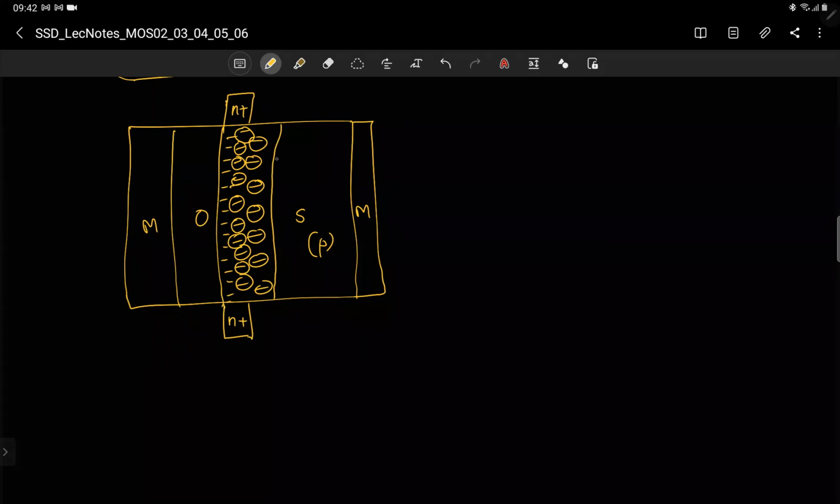If I want to contact a positive charge like holes, I have to put P plus. So in a realistic picture, how it is done is you take a semiconductor substrate, say P, and you grow oxide. I'm just giving steps, not in detail. All that process will be different, but let me not get into the process. It is called the planar process.